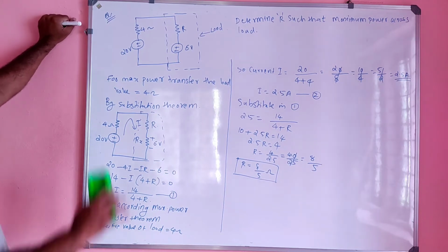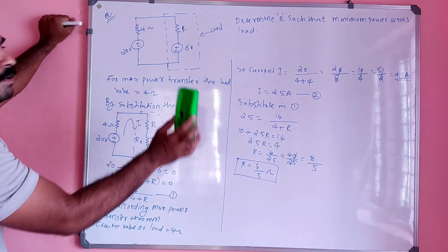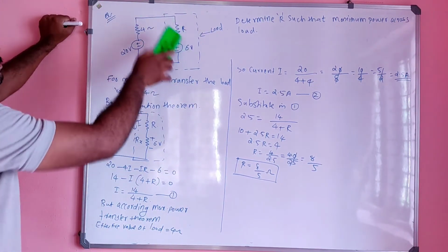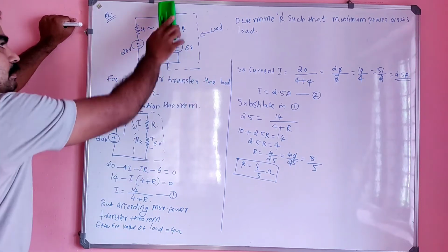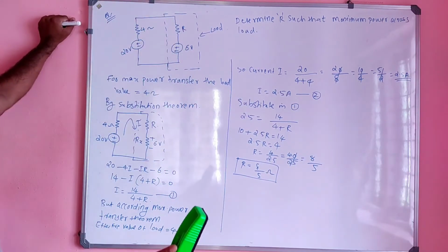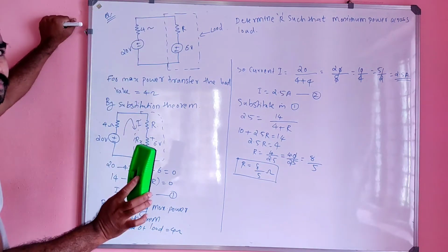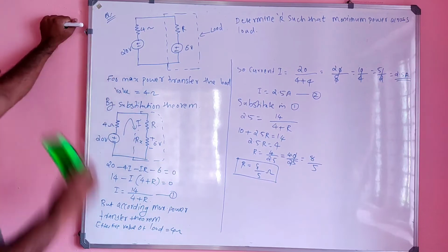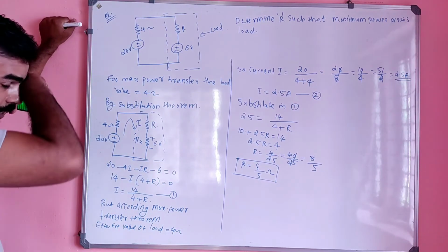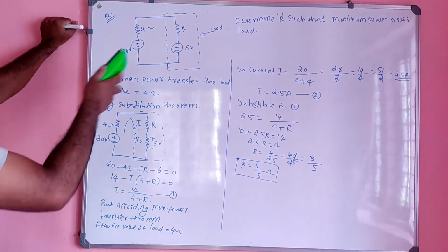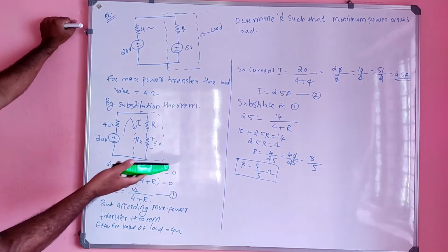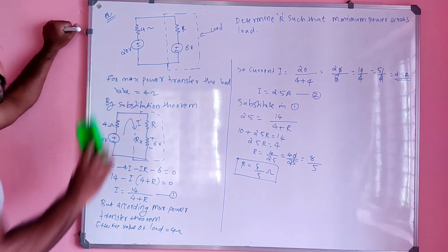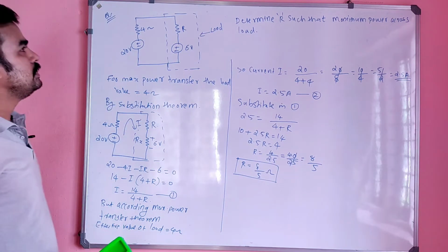Okay. So simply the concept here is the maximum power transfer concept. That means this RL, the load side RL, will be equal to this RS or RThevenin. Then the effective value of this will be equal to what? Effective value of this will be equal to this one, 4 ohm. So from that we got some conditions, and solving that condition, we will get the answer. Okay. So this problem also hardly needs what? Maximum 30 to 45 seconds only if you really know the concept. Less than 1 minute you can solve this also. Okay. So this is the concept.